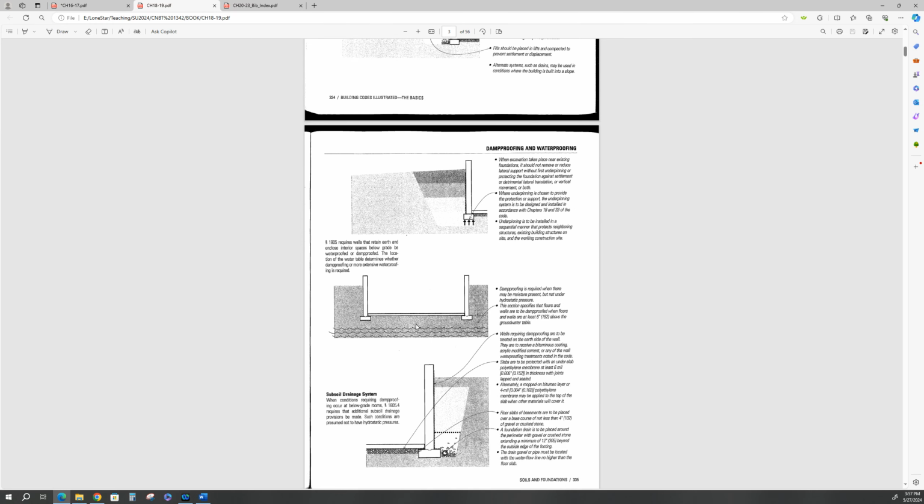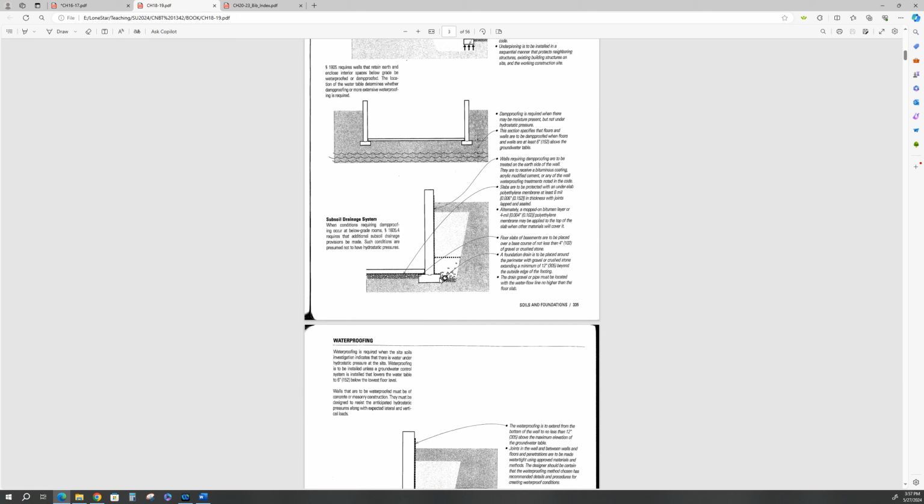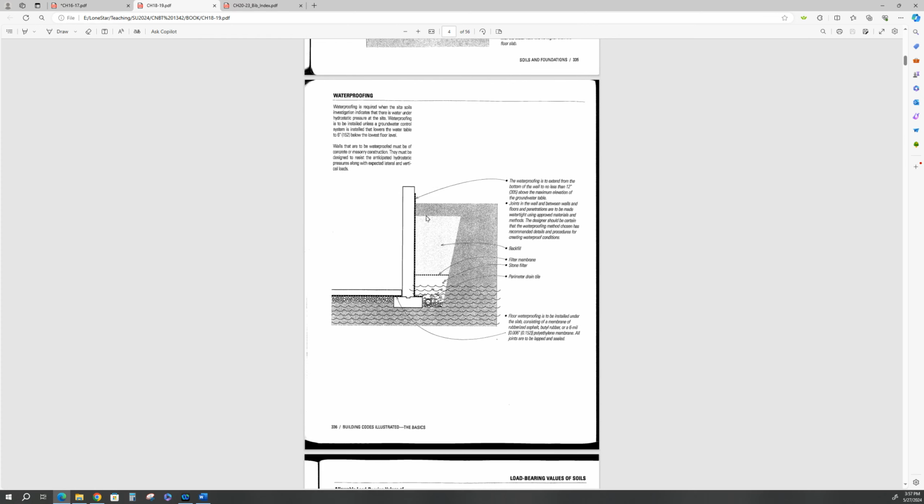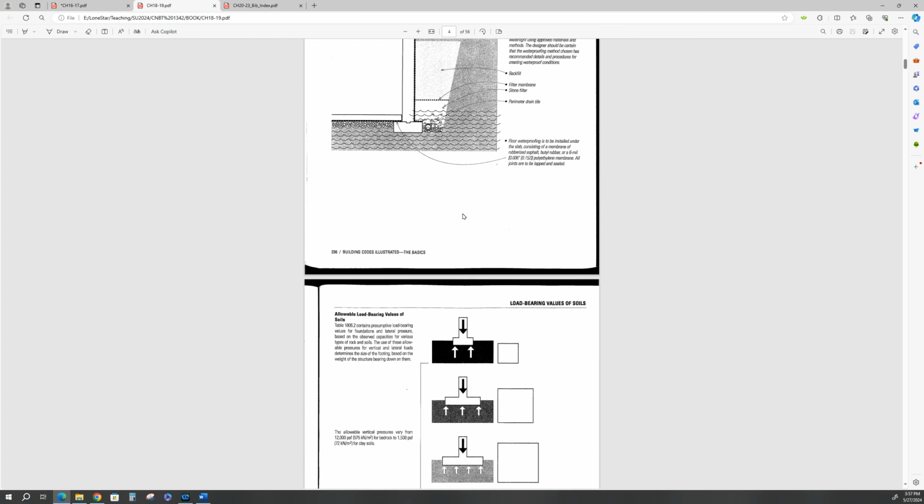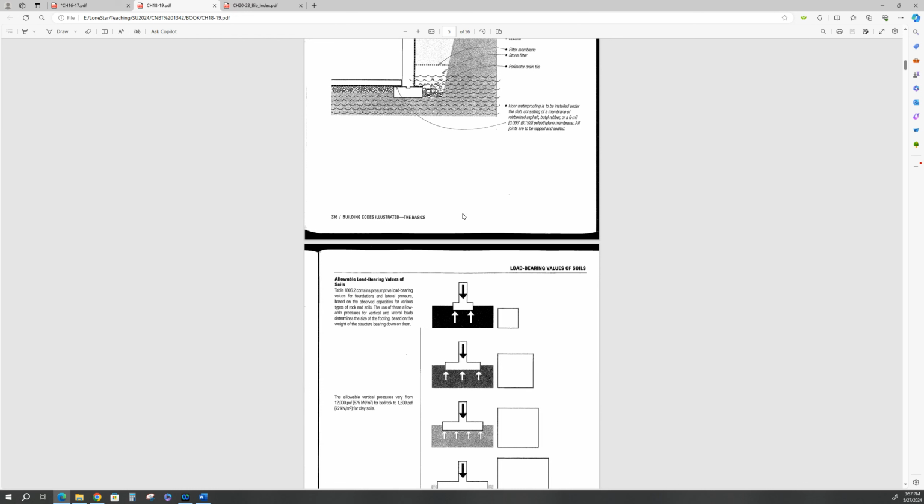They address the water table. Maybe you need a French drain, foundation drains, backfilling recommendations, because when you backfill and compact this, you're adding super extra forces onto this wall. If you got a high water table propensity, you may need to waterproof it. We went through all this in CNBT 1311.